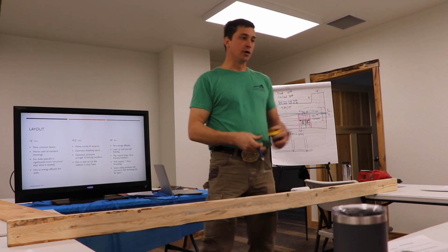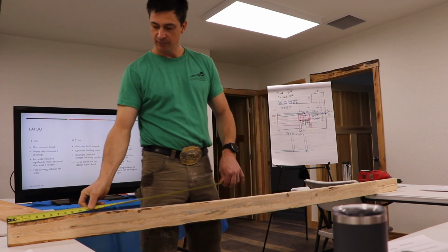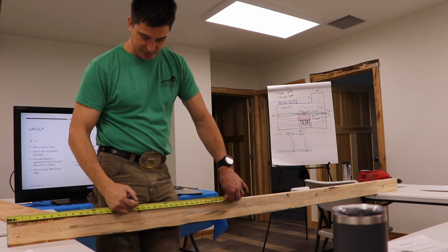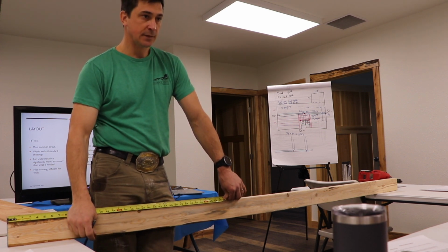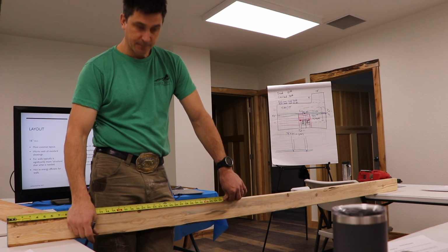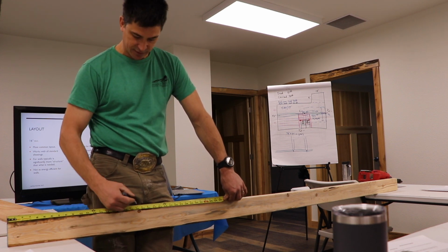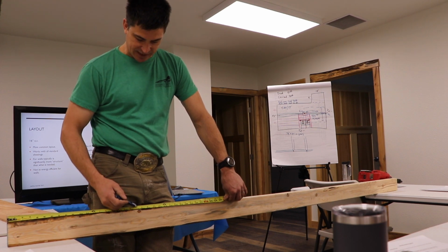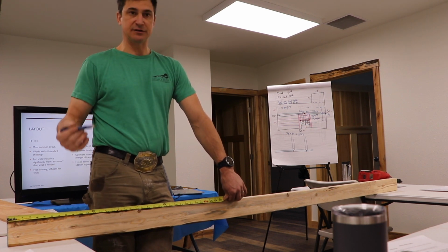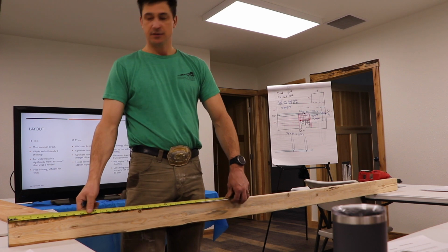So the harder one is if we're going to lay this out at 19.2. Diamond. Right. But then I'm going to go 3/4 back from that. Ooh. Well, it's almost 19 3/16, but it's rough framing.